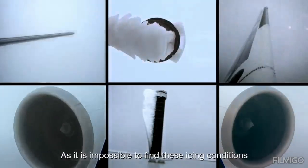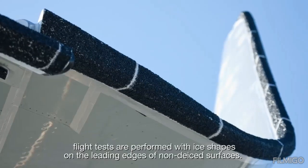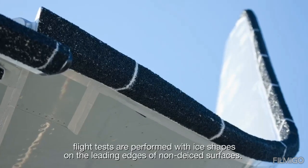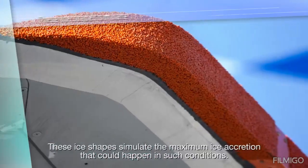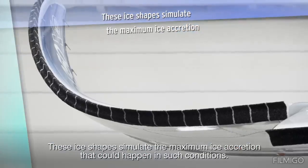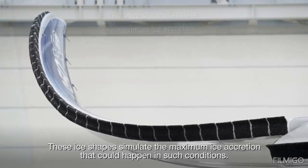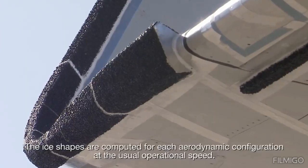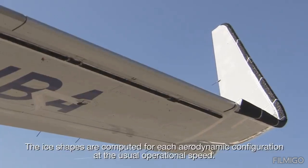They are extremely severe, but it is known that worst-case situations do exist. As it is impossible to find these icing conditions in the limited flight development and certification period, flight tests are performed with ice shapes on the leading edges of non-de-iced surfaces. These ice shapes simulate the maximum ice accretion that could happen in such conditions. The ice shapes are computed for each aerodynamic configuration at the usual operational speed.